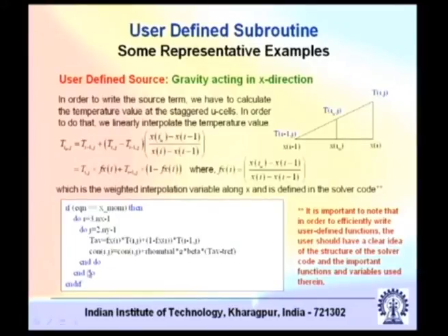So then we are writing this: con is the constant source term, like Sc plus Sp phi_p, that Sc we are calling as con. So con(I,j) equals con(I,j), that is whatever was initialized, plus rho initial, that is the reference density, into g into beta into (T average minus T reference). So that is how you simply implement the natural convection.